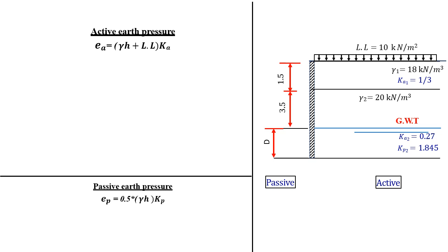First point, you have to get your earth pressure at the top, so I will call this point number 1. Then if you have a line separating between 2 different soil layers, please get your stress 2 times, 1 time just above this line and 1 time just below this line. So these are my points 2 and 3.